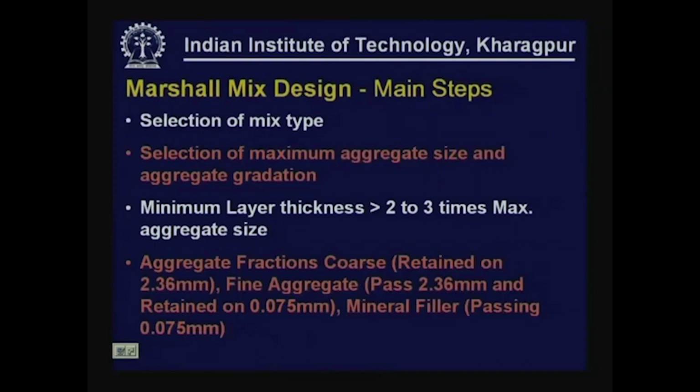and the aggregate gradation, usually most agencies have a specified gradation given for each mix. So, normally it is expected that those are to be followed unless it can be shown that deviating from the gradation specified is for good, and if you can convince the agency, then you can go for other gradations other than what has been specified by either MORTH or other gradations.